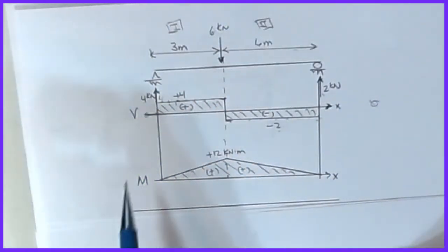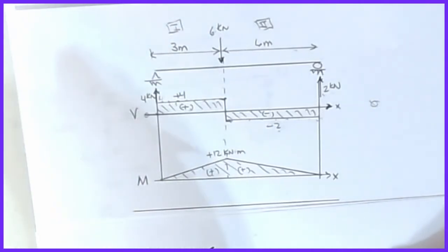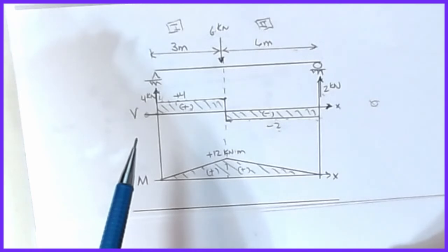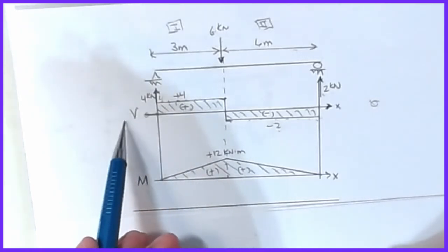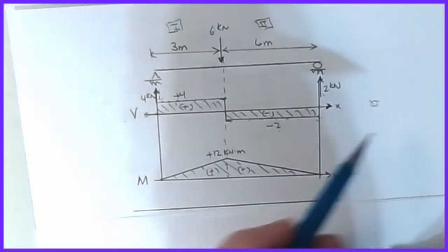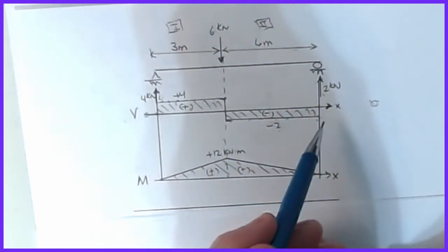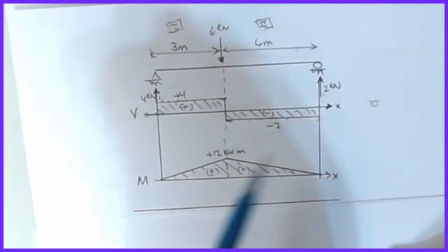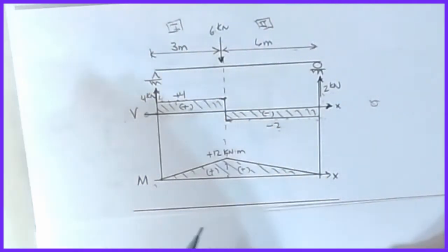as I come off the beam. Shear and moment diagrams are really pretty cool because you always know if you drew them right or have a good idea. If you don't start at 0 and you don't end at 0, something went wrong. That becomes a real good way to test, so you should always do that last calculation to test it. The same thing for the moment: I should start at 0, I should end at 0.